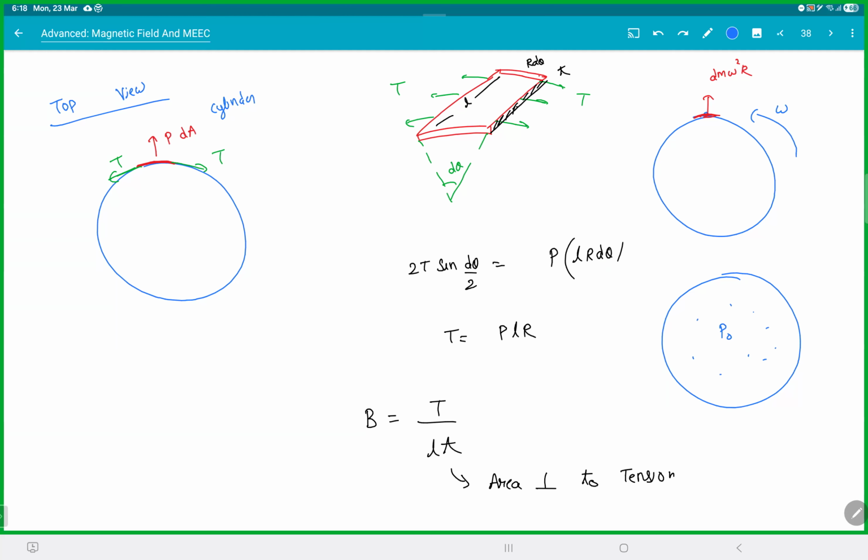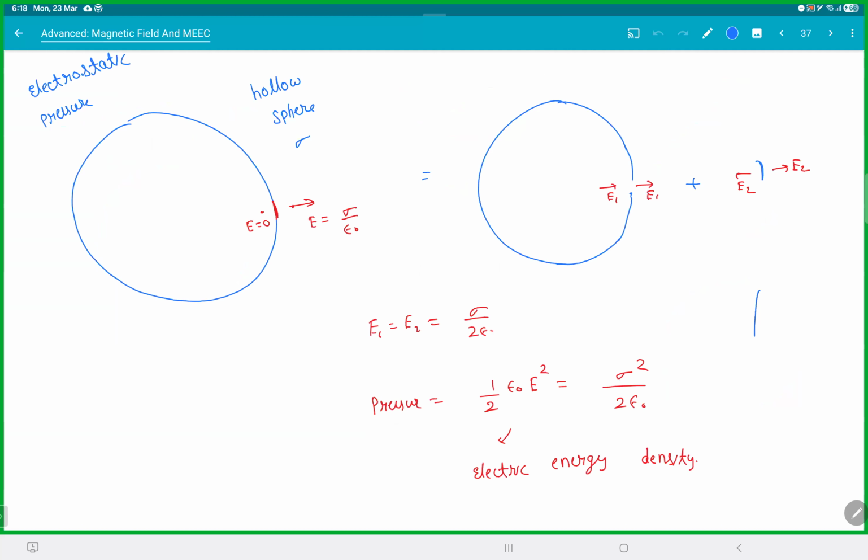In this question, we will take a half shell. Again, I'll give you some thickness and all. Here also the idea is the same. So the pressure is acting this way. So the force will be pressure into projected area, P into pi r square. And where is the stress acting here? The stress is acting on this small cross section here. So this will be the tension. So that tension by area. So here the breaking stress will be tension by 2 pi r into small t. That will be the breaking stress in this case.